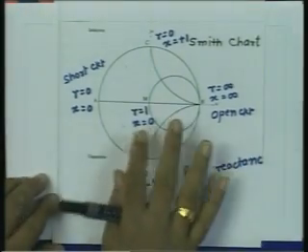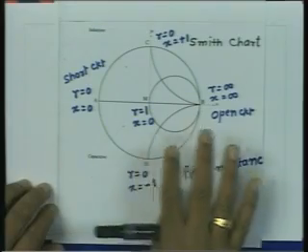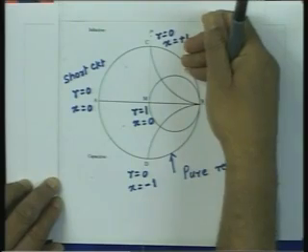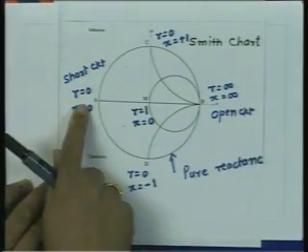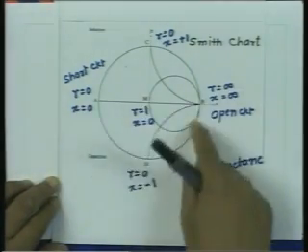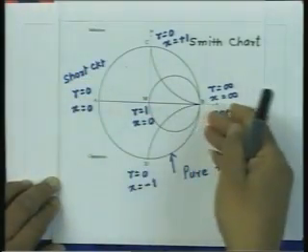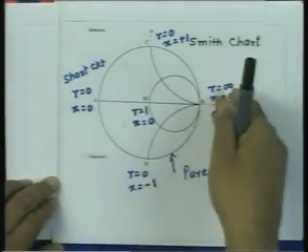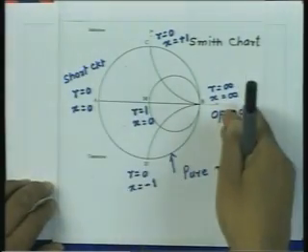represents capacitive loads, and the negative value of susceptance represents the inductive load. So, if I keep the Smith chart fixed, then while doing calculation with the admittances, the upper half of the Smith chart represents the capacitive load, the lower half represents the inductive load. This is the open circuit point and this is the short circuit point. Since the resistance circles are symmetric, there is no difference. So, replacing R by G essentially tells you the G value is increasing from 0 to infinity as we move on this side, but the point is going from the open circuit to the short circuit.